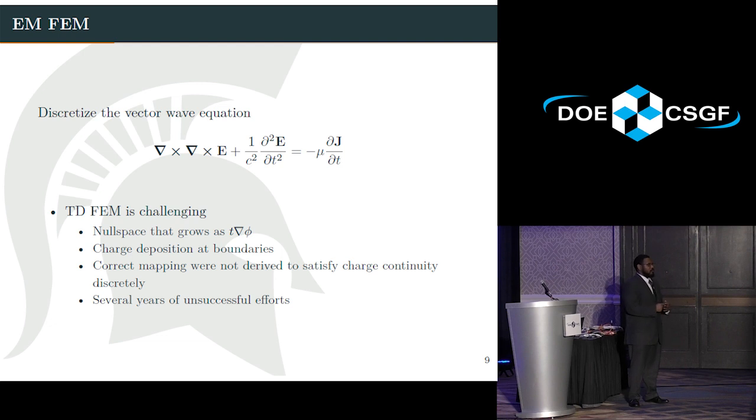And furthermore, that nice thing about the finite difference time domain method, where your fields are nice and continuous, if you introduce new material properties, a dielectric, let's say in your domain, you need those discontinuities we talked about earlier. Your electric field, the normal component, needs to be discontinuous.